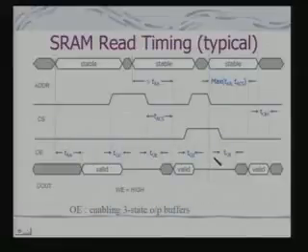Now let's look at this timing in more detail. So this is a typical scenario where I have also assumed that there is, at the output stage, a 3-state buffer. So one of the states is a tri-state high impedance state, and I have got the output enable signal which enables the output buffer. So here we have got more timing parameters which I have shown in this context.